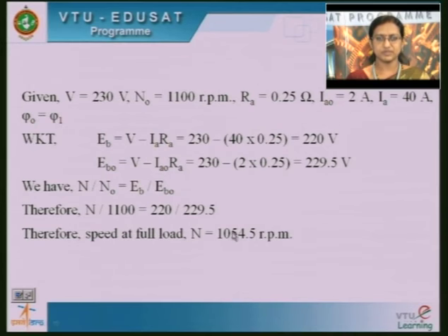Now you observe these two: at no load the speed is more, at full load the speed is less. That means as the load increases, the speed decreases, because the speed is inversely proportional to the load current.